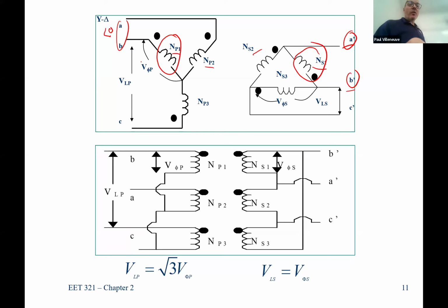When you're looking at individual phase voltage, they're exactly the same. Yes, sir. You can always put an opposite transformer. You can put a delta Y transformer to give you the 30 degrees back. But most times it's not a problem because you're not connecting two different sources at different phase shifts.